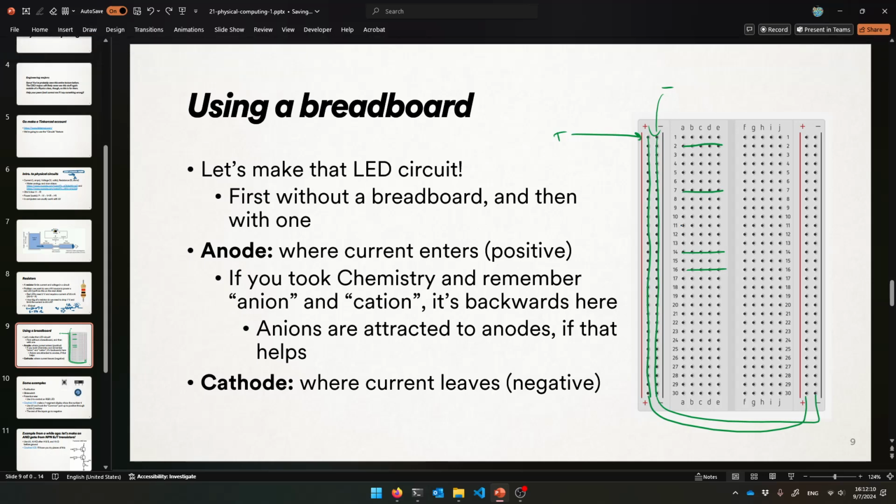And so if we want to make our little circuit, here's what we'd probably do. We want to go from power, the positive end of our battery, to this rail, and now this whole thing is powered, right? And then we want to connect, I don't know, a resistor. So we put a resistor in one hole down from here to here, and now there's positive resisted positive coming through here. And then you can pass along a wire from here to here. Maybe you can put your LED from here to here, I don't know. And then bring it into negative over just like that. So see how it's going to connect positive to here, to all of that. Resisted across, now this is all connected. Then over to here and into, eventually the circuit is completed, okay? That's kind of the idea.